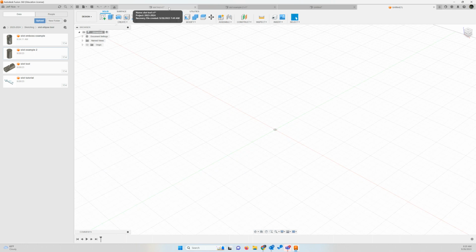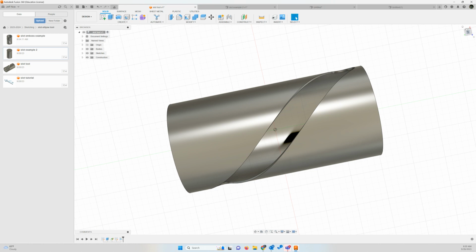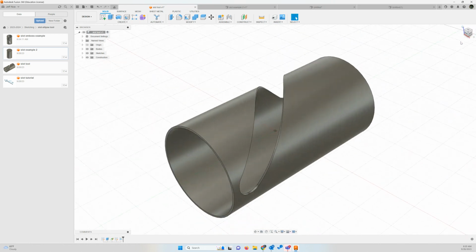And we're going to create this design now. From the home position there, we're going to create our sketch. It's going to be on the front back plane. We're going to extrude it back. Our sketch is going to be on the origin. Notice here, there's our origin.